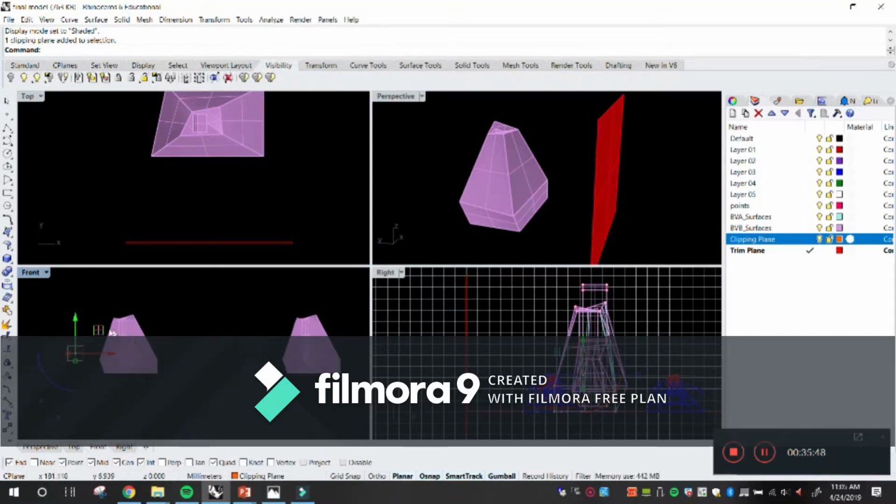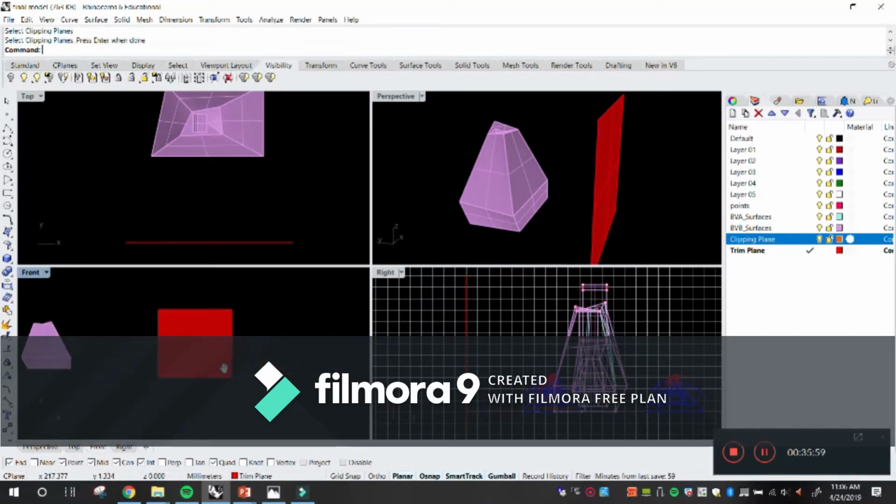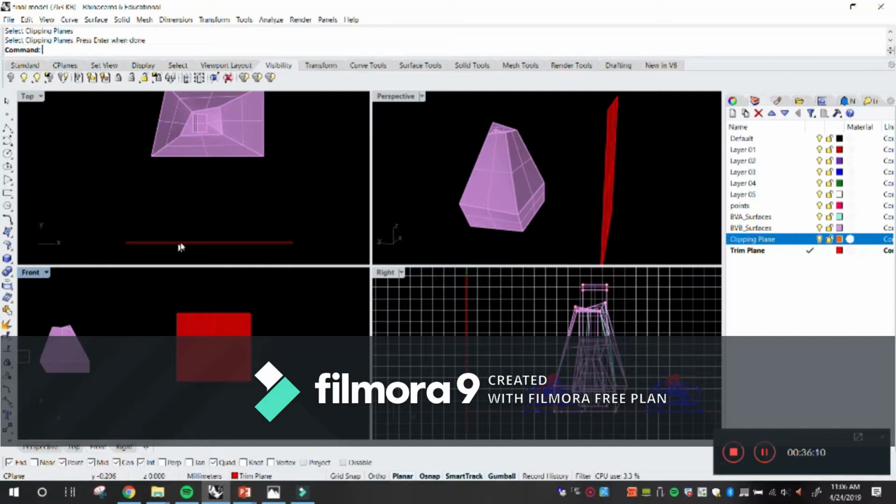If I select it now, let's go back to visibility, disable the clipping plane. Select it now on this viewport right here, right click, there we go. I'm glad that came out because we disabled the clipping plane in our perspective viewport, which is where we were working, but it wasn't disabled on the other viewports. I don't know if there's a disable all. I don't see that. I think you have to do it per viewport.